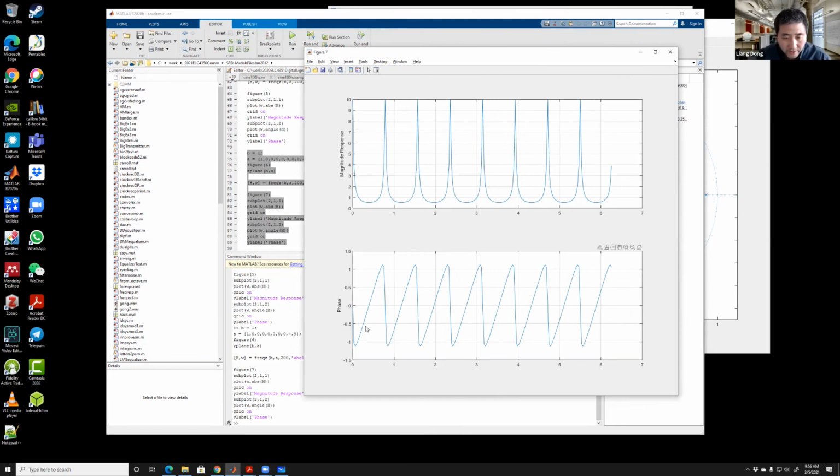And then we check the phase. This phase is nonlinear. It has some curvature here. It's not a straight line. If you connect it, it's not a straight line. Because again, this is an IIR system. I have the numerator as constant 1, but in the denominator, we have a polynomial. We got some values of a's there. And that gives me some feedback that tells me that the system has nonlinear phase.